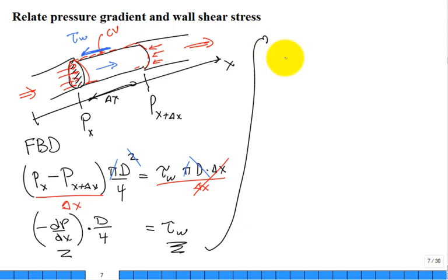From our previous, where we had external flow, there was this friction coefficient, the coefficient of friction, C sub F. What was it defined as? Well, we had the wall shear stress, and we normalized it by 1/2 rho U squared. Sometimes if it was external flow, we talked about U infinity, but here we have the internal flow in a pipe. What's our single velocity of interest that makes sense? Our mean velocity in the pipe, right? So 1/2 rho u mean squared.